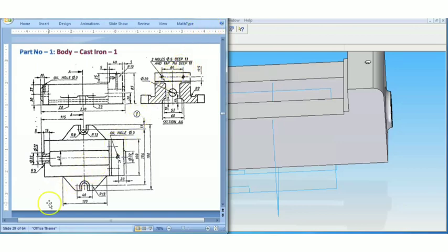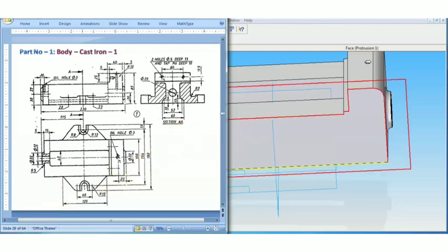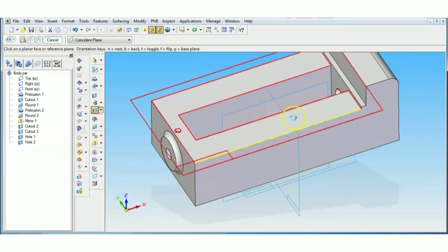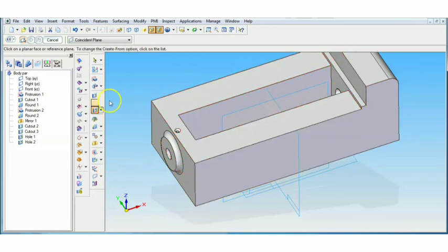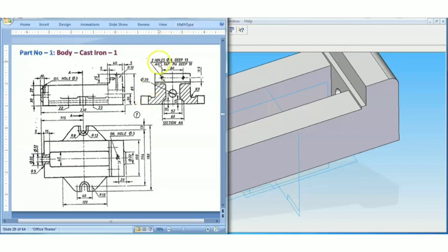So to make the holes, now to create the holes here on this plane, I will be going for the hole option again, and we are going to create the two holes of diameter 6, deep 13 and tap M6, deep 10. So diameter here it is shown as 5, we are taking it as 6, diameter 6.